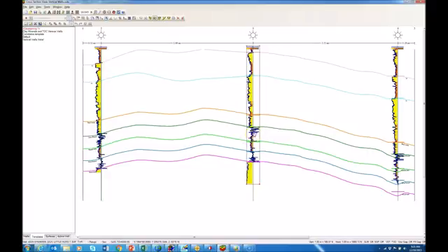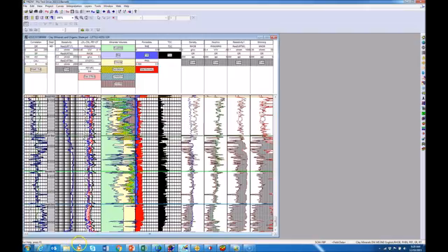I'm going to select this well, and we'll examine this well in PRISM, our petrophysical application. You're looking at PRISM, the GeoGraphix Petrophysical Analysis application. I'm running a multi-mineral model looking at 6 different phases of competent components of sandstone, limestone, and dolomite, and also the shale clay components of kaolinite, illite, and chlorite.